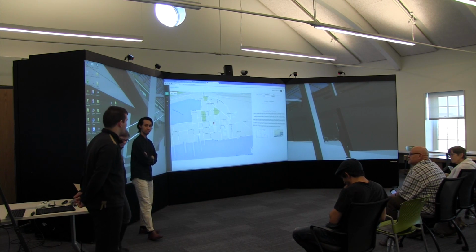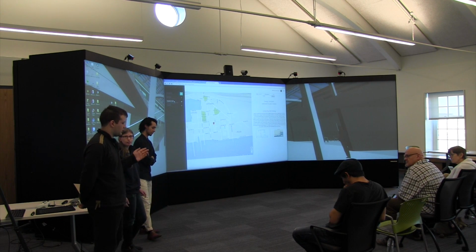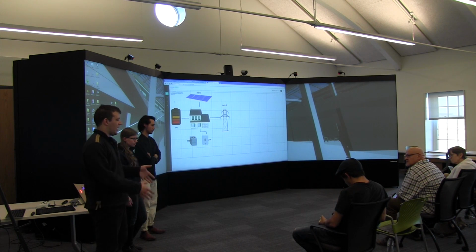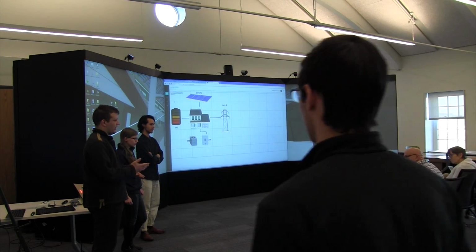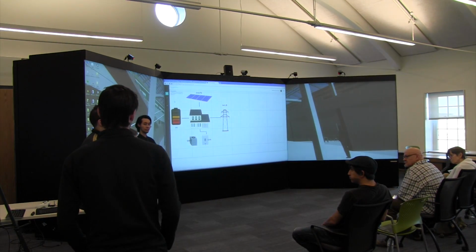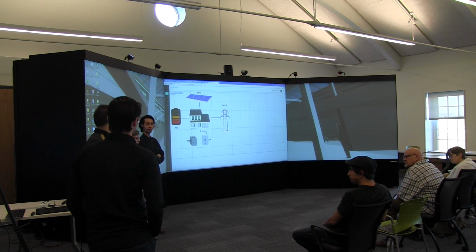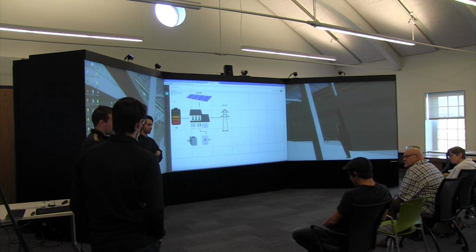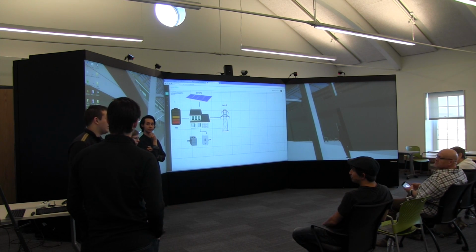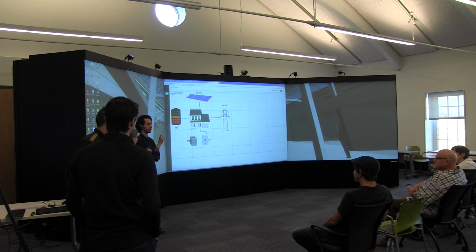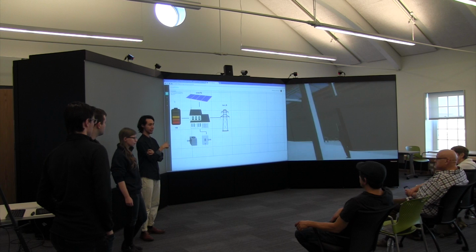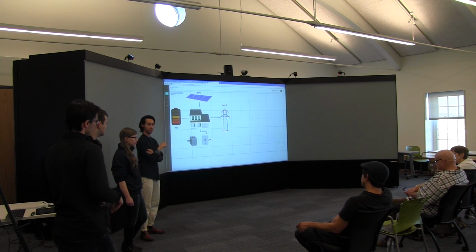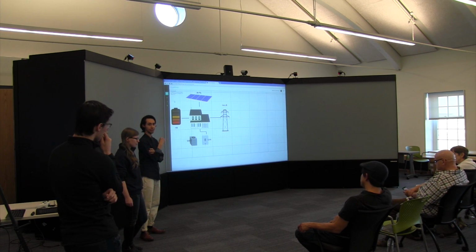The idea here is that the battery in the house right now is locked into the frequency regulation, so they're contractually obligated to always be on demand in case there's a need. So if you can predict whether there will or won't be a need, and you know there's not going to be one, you can then use it to sell. The second model we built determines, during the day and based on real-time inputs, when's going to be the best time to sell. If you did it automated, you could probably get the biggest return. What we didn't mention is that you get an hourly constant rate if you meet your quota for frequency regulation. Even if you're not discharging at that point, you're making so many dollars per hour.